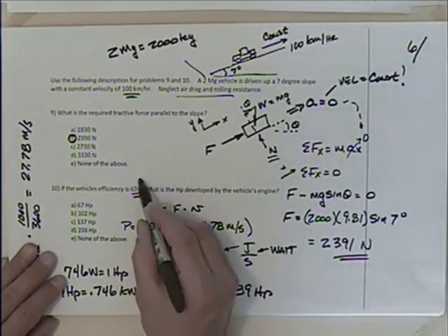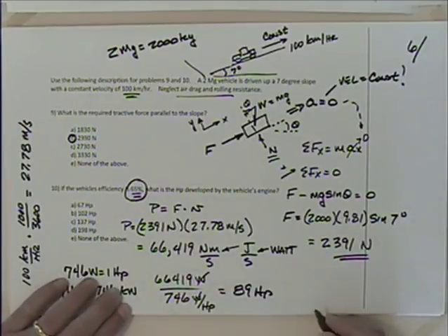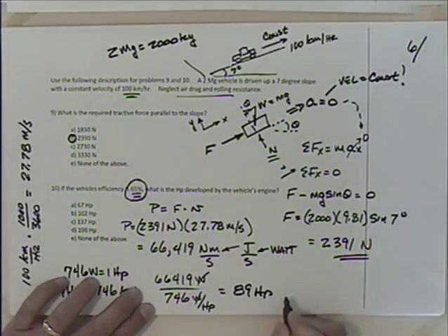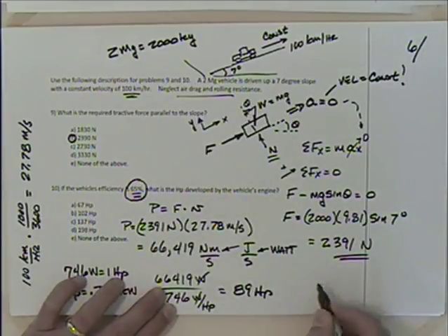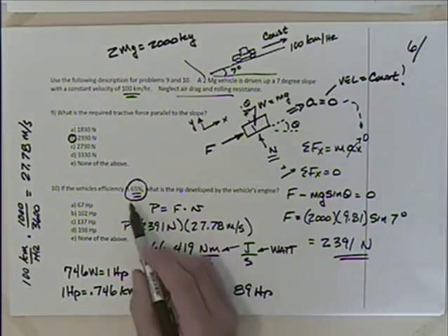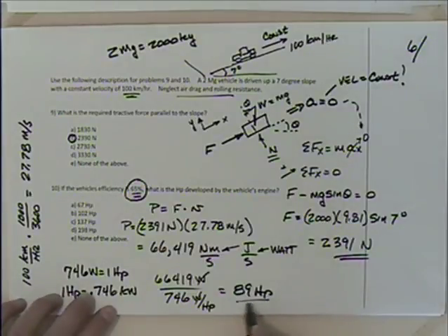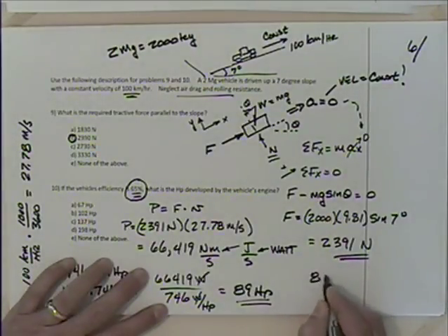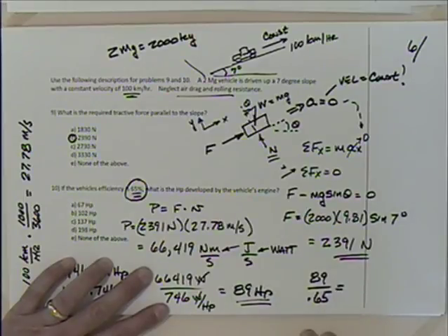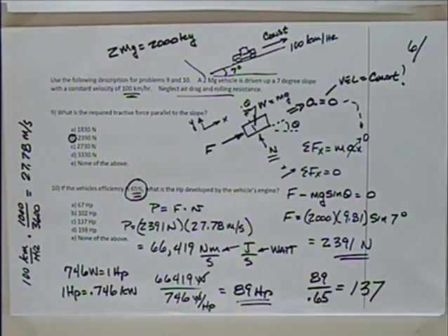And again, accounting for this can be rather tricky. So we'll just take that number on face value. I don't know whether it's a good number or not, but we know we're going to have to provide more power. If we were to take this 89 and multiply it by 0.65, we would get a number smaller than 89, which doesn't make sense, because ideally we need 89, and then we'd be saying that we need less than that. So I'm going to take this 89 and divide by 0.65, because it's in percent, of course. So 89 divided by 0.65, I come up with 137.